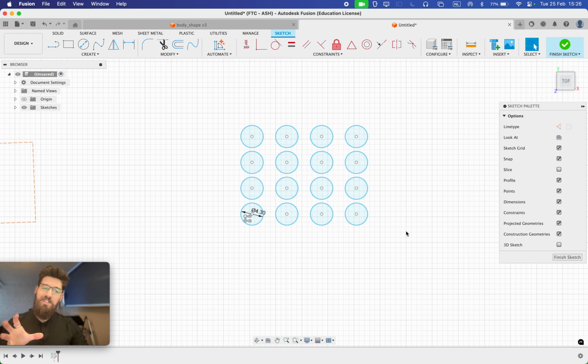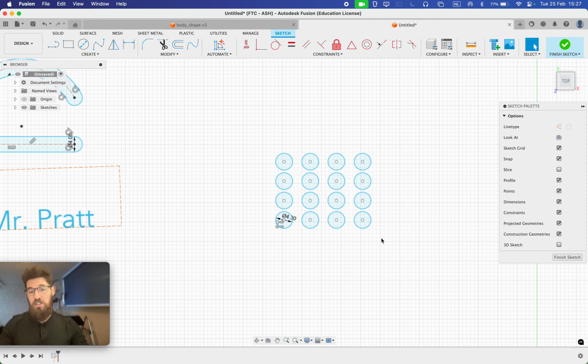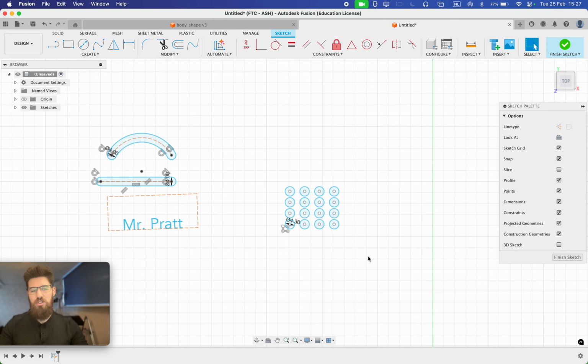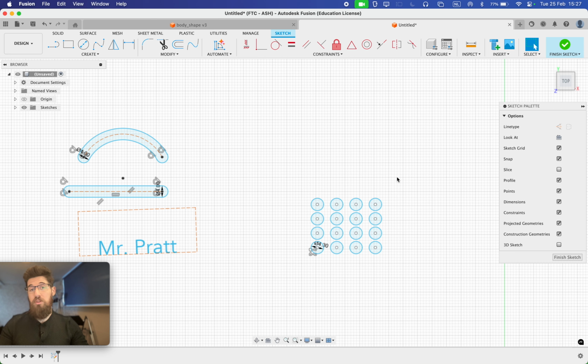Now, there is a danger with using the rectangular and circular pattern in sketches, in that it's really going to slow down the performance of your models. Fusion says it's best practice that you should make rectangular patterns for simple sketches, and then instead you should mirror them out as solid bodies instead. But for today, I'm just showing that you can do this in the sketch interface, but it's recommended that you don't do it inside the sketch interface. Although that's something you're going to find about Fusion, there are 1,000 ways to skin a cat. Lots of different ways to do the same task.